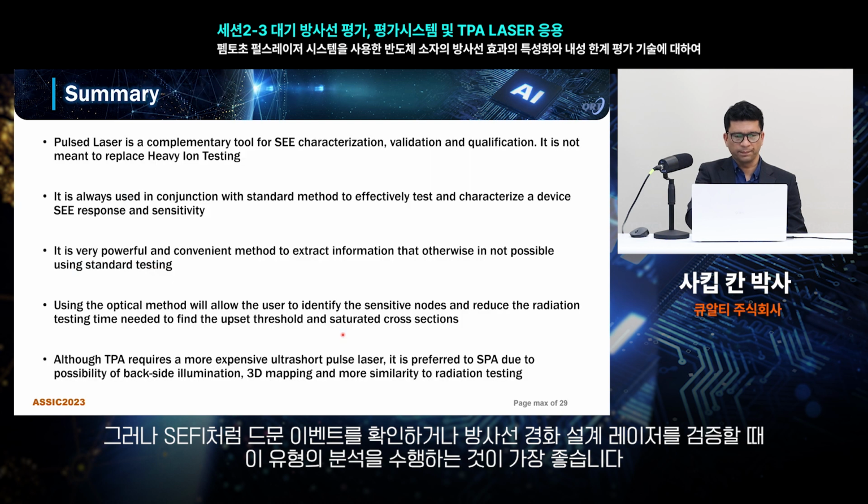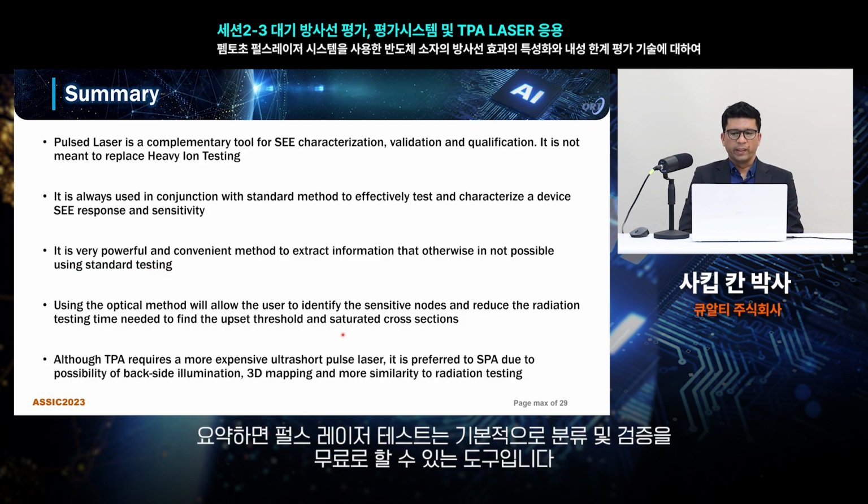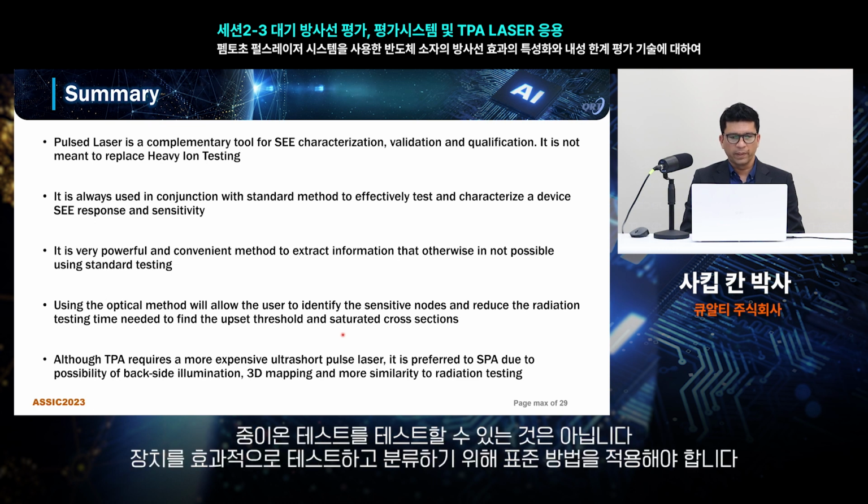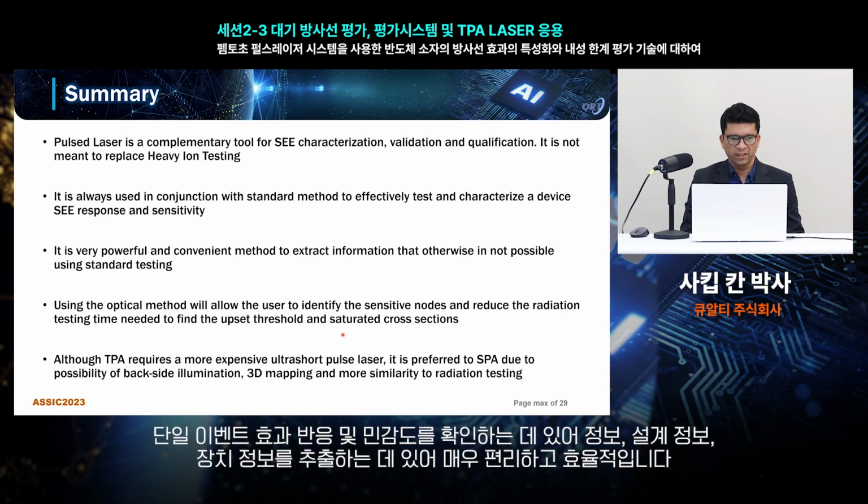to perform those types of analysis. So in summary, pulse laser testing is basically a complementary tool for characterization and validation. It is not meant to replace the heavy ion testing. It is always used in conjunction with the standard method to effectively test and characterize a device's single event effect response and sensitivity.